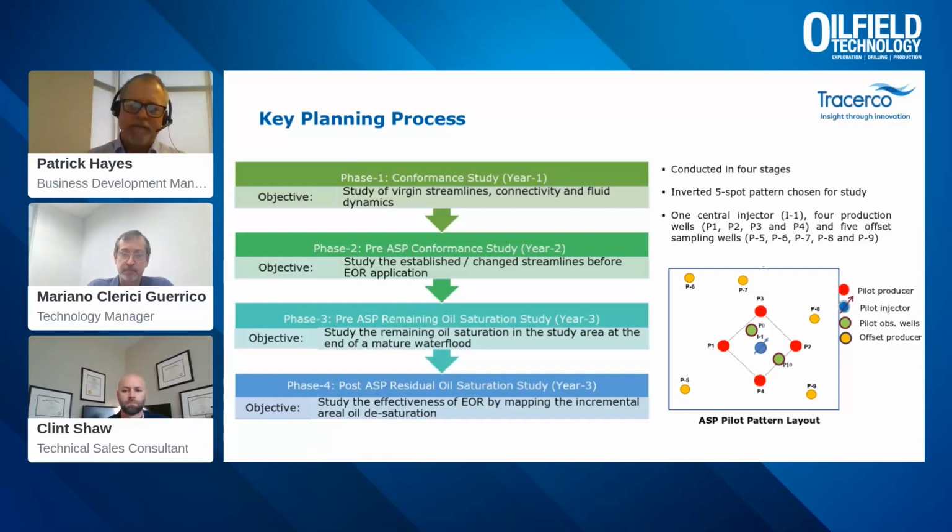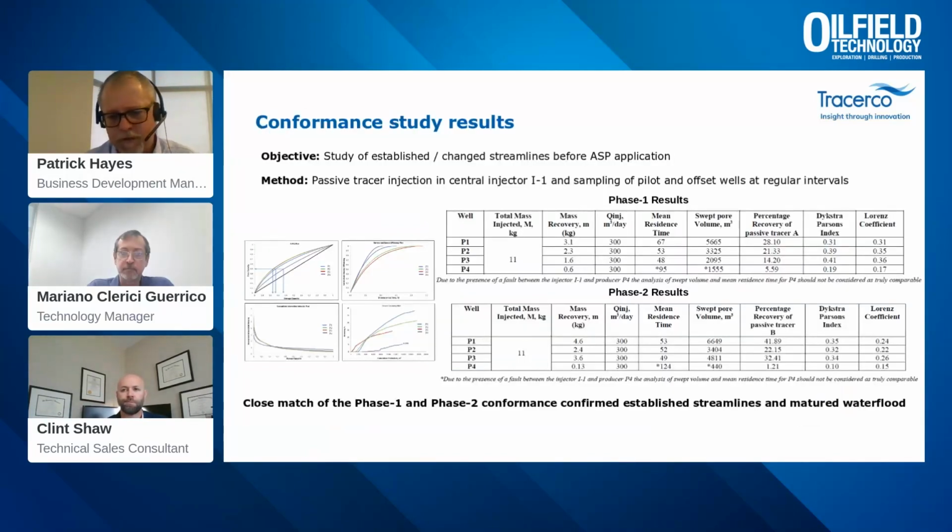So we had a pilot study, initial injection, a time frame of conformance, an evaluation of change of that conformance and reservoir communication after a year of production, and finally the initial injection of partitioning tracers to calculate initial remaining oil saturation, followed by the ASP application and a secondary test of its conformance and what remaining oil saturation existed.